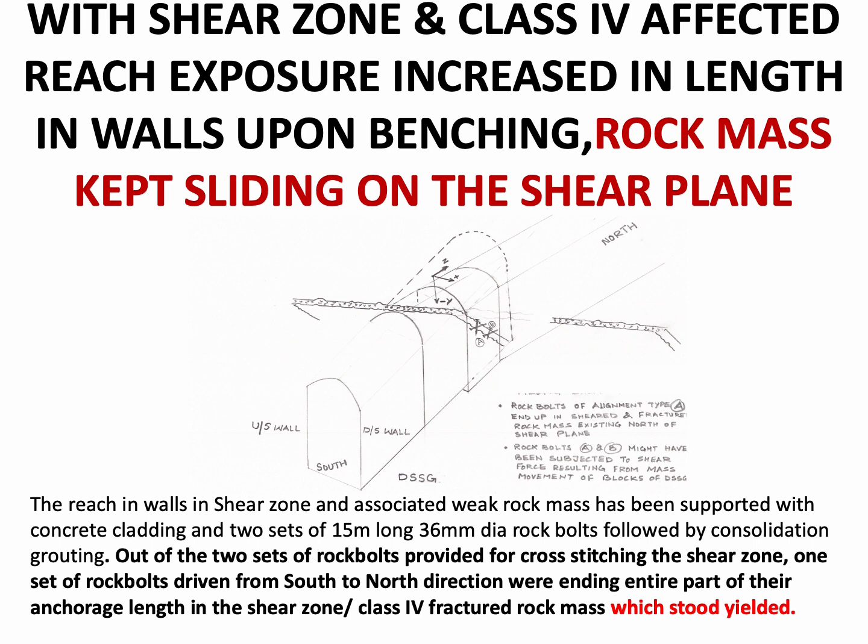But what was happening was that one set of shear rock bolts was having its end landing in the shear zone and fractured rock only, while the other set was having its anchor end ending in the sound rock. So that was effective, but this set, with their anchor to be provided within the fractured and sheared zone, was not effective.